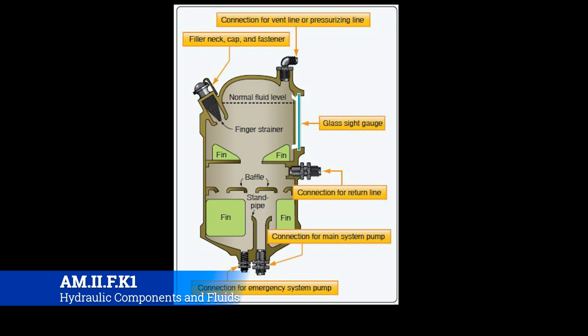Now, the baffles are really simple. They're basically little metal structures that just disrupt the flow. If it all starts going one way, it hits a wall and then has to go through these very small ports. By the time that hydraulic fluid starts to bypass that baffle, the airplane's basically corrected itself, and so the effect you get is very stagnant hydraulic fluid that can't just move around all over the place, and that's why they are there.